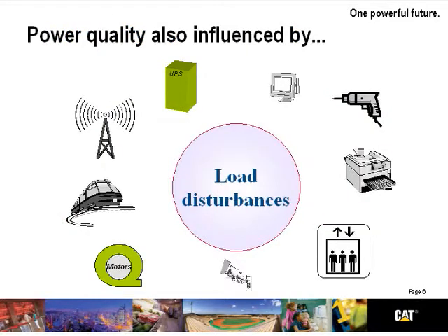When you look at the load side, and that's the things that happen in our own buildings, we see lots of opportunity for things to cause interruptions or anomalies to our power. Think about working at home with a drill and you get static on the radio, or firing up a hairdryer and you see the result of that on your television set. Well, in our commercial buildings, our retail space, our industrial spaces, even our data centers, there's lots of ancillary loads that put noise and disturbances back into the system that the UPS must also be able to deal with.